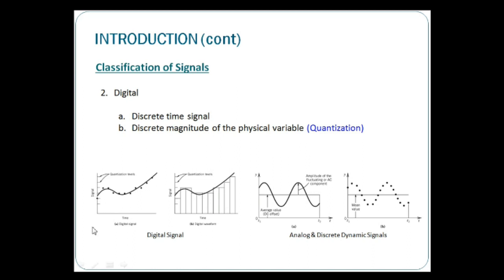If you plot this signal over time, you discretize in terms of time. So that delta t, the time between two samples, is decided by, if you still remember, your sampling frequency or sampling rate. So 5,000 samples per second: every 1 second you have 5,000. So in between two samples is 1 over 5,000, which is your delta t.